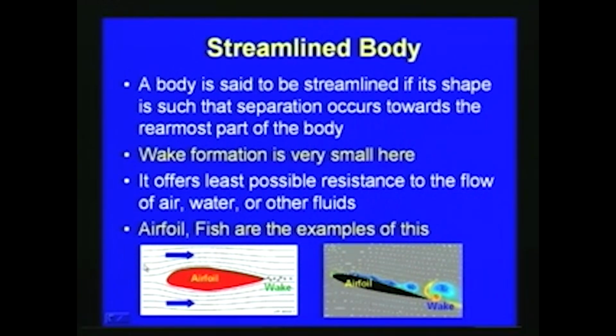Here, whenever the airfoil is placed like this, the flow is coming like this, and the wake formation is small because the airfoil is streamlined. The drag effect will be much less, especially the pressure drag.